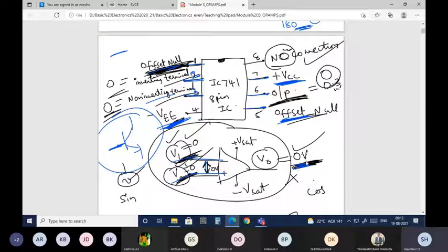You may have some output voltage. It might be due to some mismatch in the input circuit. So that is the reason you may have some output voltage here. That output voltage will be made equal to 0 by setting this offset null. Or in another way, consider both V1 and V2 as common mode signals. V1 is equal to V and V2 is also equal to V. Both are given with the same amplitude. So the same signals are provided at V1 and V2. So what happens? The difference between them will be equal to 0. So the output should be equal to 0.